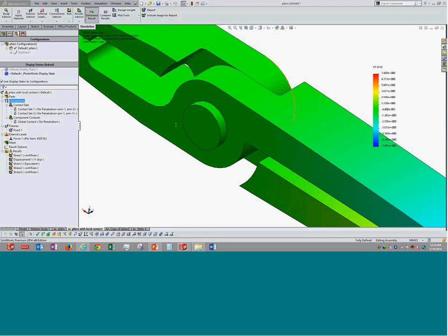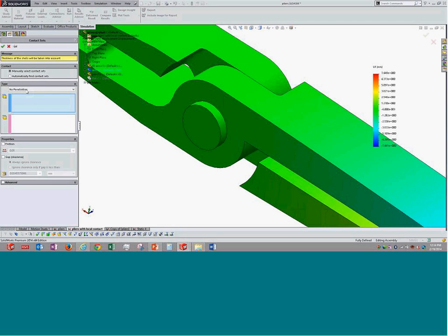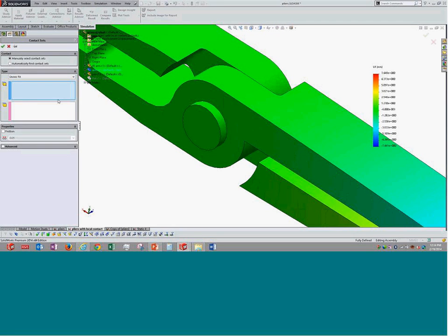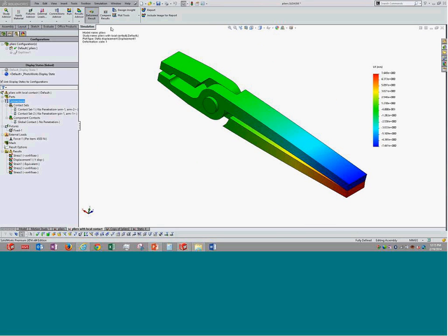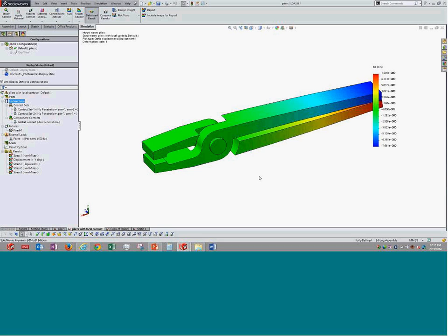There are cases, for example shrink fit, where you simulate it by using the shrink fit option. It is selected under that option, and afterwards the software will calculate to get the parts back to the original shape, and then it will go ahead. If not, we need to overcome the interferences between parts before you do any analysis in Sim. Does anyone else have any other questions on the contact discussion that we had in the last half an hour?